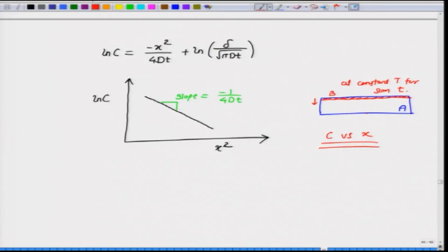Then they measure the intensity of radiation on the surface, and the intensity of radiation is related to the concentration. And to get the profile of intensity versus depth, we can remove the layer by polishing, and every time we remove small layer, measure the intensity, again we remove the small layer on the surface, measure the intensity, and that is how we experimentally obtain these profiles.